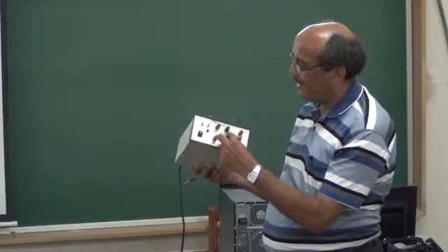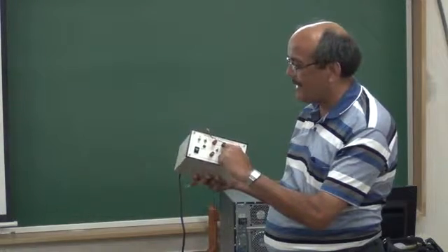So you are going to perform the experiment for all 3 capacitors. First of all, you select one capacitor, let us say 10 microfarad. Here we have this switch. This switch helps us to find out the value of the internal resistance which is inside the box. At the same time, it also gives us the liberty of connecting our own resistance that we want to measure.